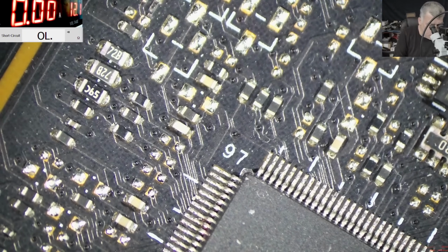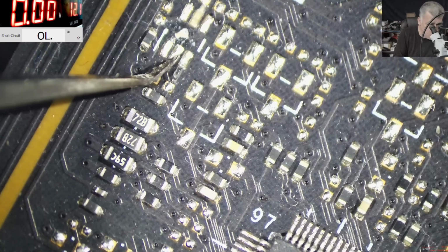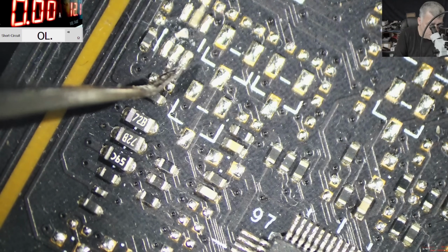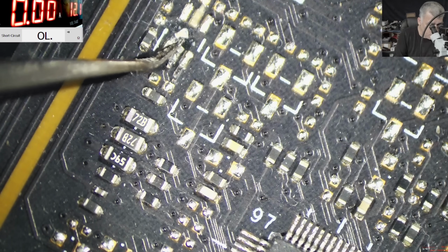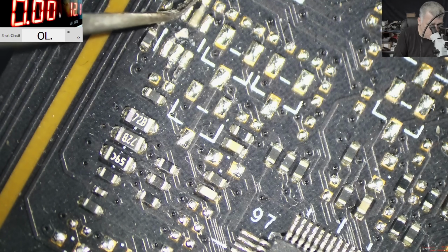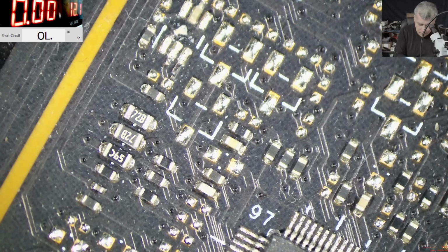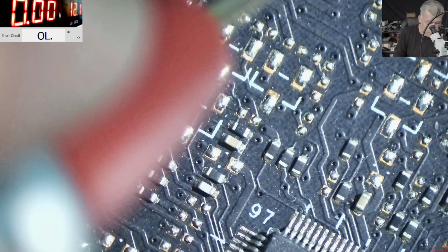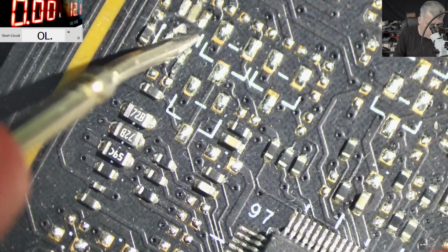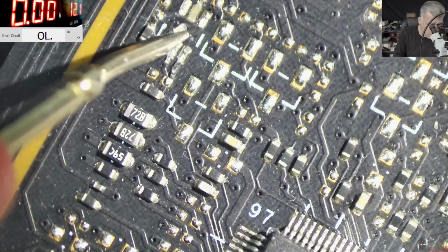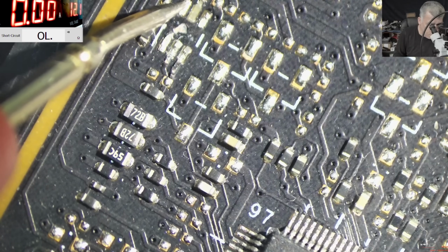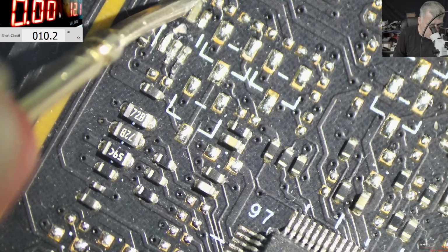So what do we know? We know we have two pins to 3.3 from the main power rail. That's huge. Here we have ground. Not sure what this is switching, but it must be important. Based on the fact this pin has 10 ohms, it can be something important here. And here is ground, so we have two grounds. Here you have 3.3, and here you have 10 ohms.